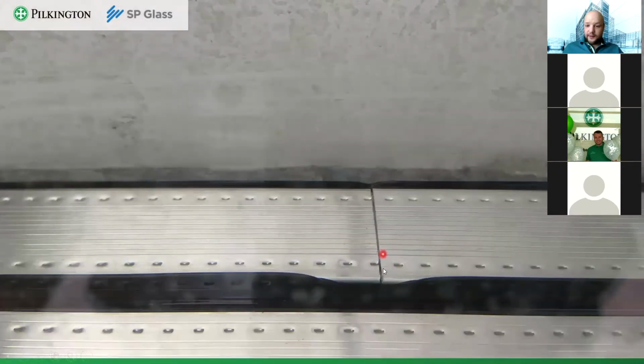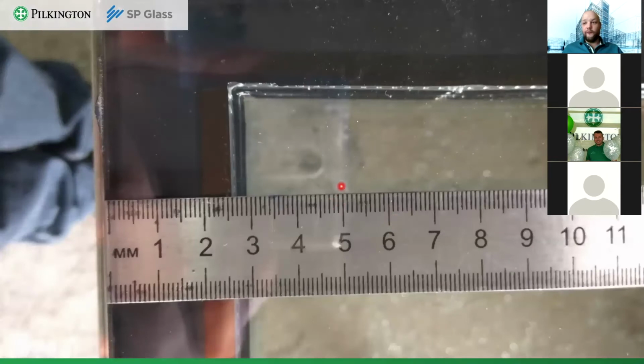While here you have a break. Here, again, one of two most important places in your spacer, this is a connecting part. It should be sealed very, very well. But in this case, as is seen in the photo, it has a break. And by all standards, a butyl break is considered a fault of the IG unit, because through the break, water vapors can get in and the water can condensate inside the IG unit, obviously making it faulty.